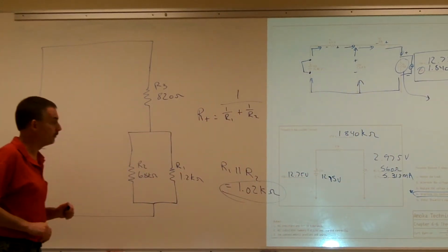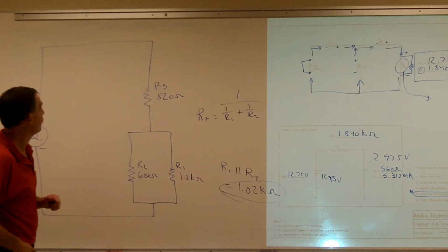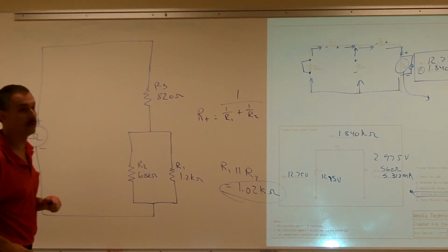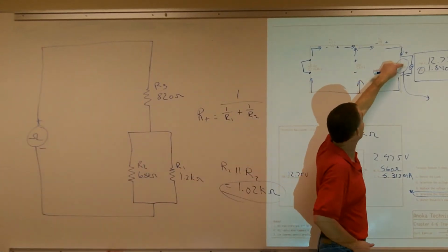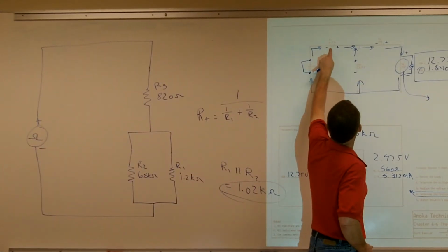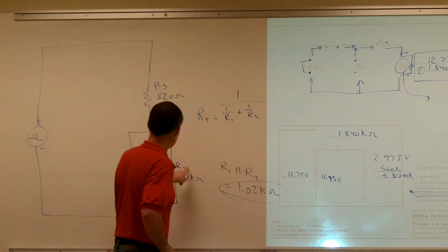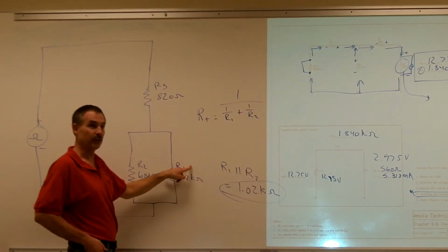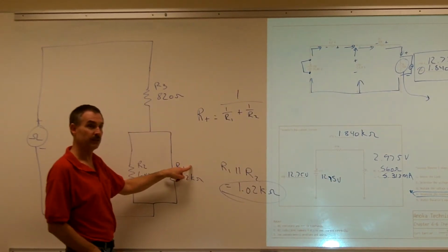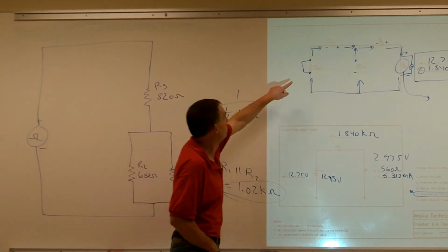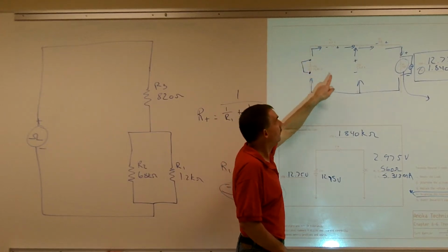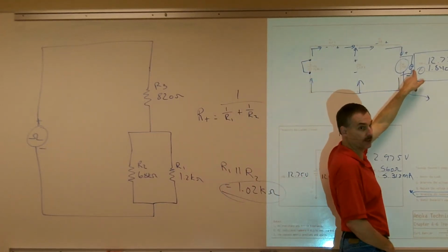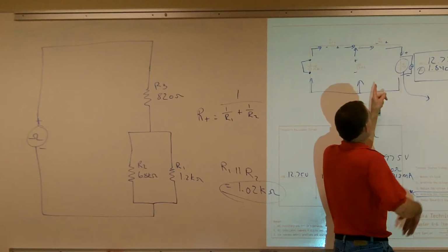What happens to that first resistor in the circuit? This one here? No, on the far left. Yeah, that's this one right here. See, it doesn't look the same when we change the circuit up. Because remember, we shorted this power supply out, so that just becomes a line now. We're using our ohm meter as our source, and we reconfigure it.